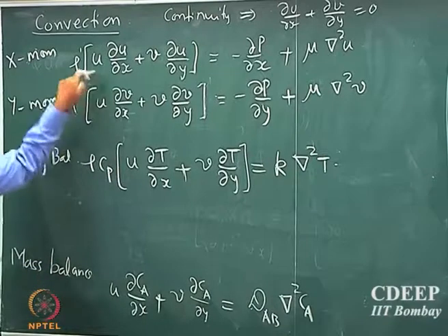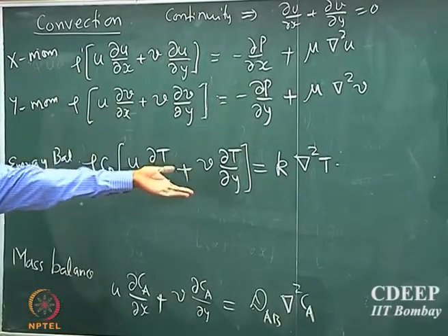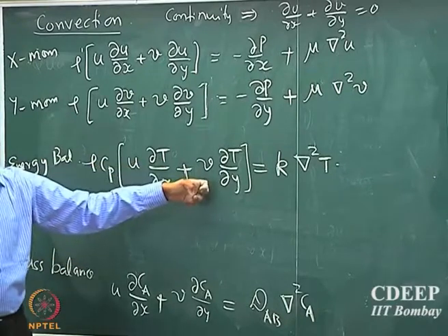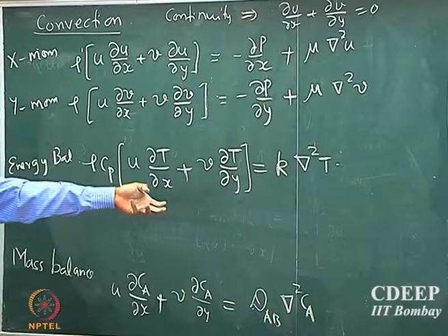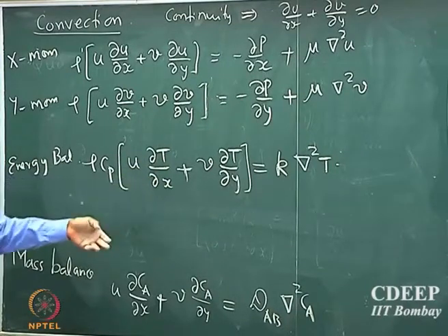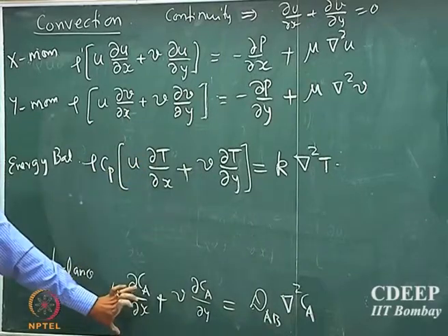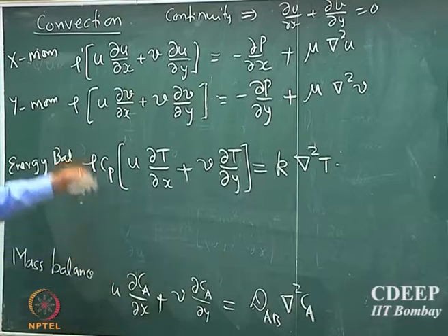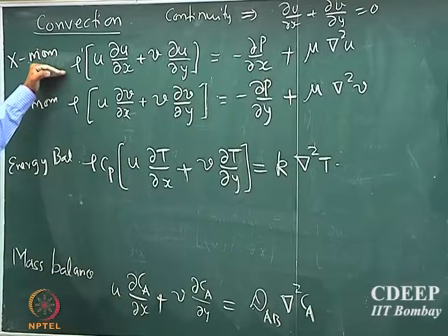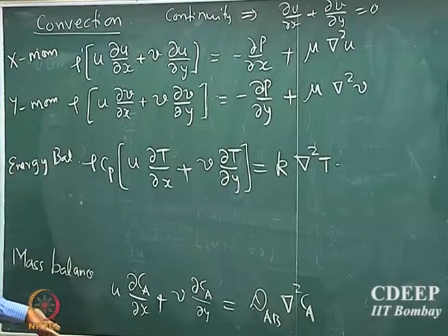Okay. So U and V, if we assume that the viscous dissipation is 0, then U and V are completely independent of the temperature, right. So if we assume viscous dissipation is negligible, then U and V are independent of temperature, and therefore these two equations are linear with respect to temperature and concentration. So the real task is to find what is U and what is V. If we know that, we know exact solutions of this. Okay.